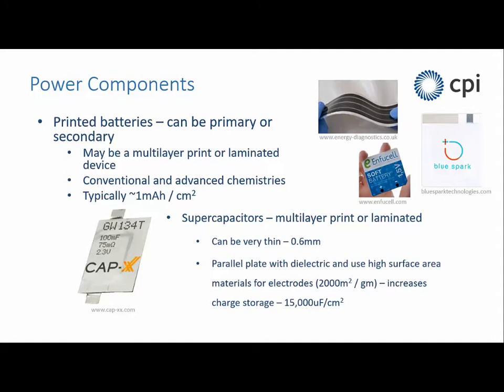You're welcome to come up and have a look after the presentation. But this is a battery that has about a 30 milliamp hour capacity. I can bend it. It works perfectly well while it's bent, and it will straighten out afterwards as well. It's produced in a very simple printing process. There's no lithography or anything like that that's needed for that. It's conventional printing sort of processes. And these devices really can power electronic systems for substantial amounts of time, even though they sound like rather low energy capacity. If you design your circuit to match, then you've got a good effective system.